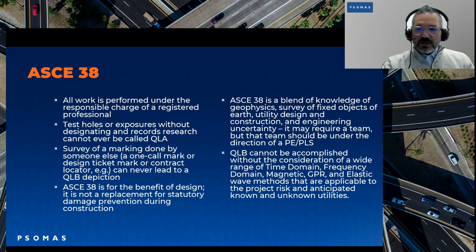ASCE 38 is a blend of knowledge of geophysics, survey of fixed objects, earth, utility design and construction, and engineering uncertainty. It may require a team. In fact, I would say it does require a team under the direction of a PE or a PLS. QLB cannot be accomplished without the consideration of a wide range of time domain, frequency domain, magnetic, GPR, and elastic wave methods that are applicable to the project risk and anticipated known and unknown utilities. All the different types of equipment should be used if you're going to establish a proper QLB designation.